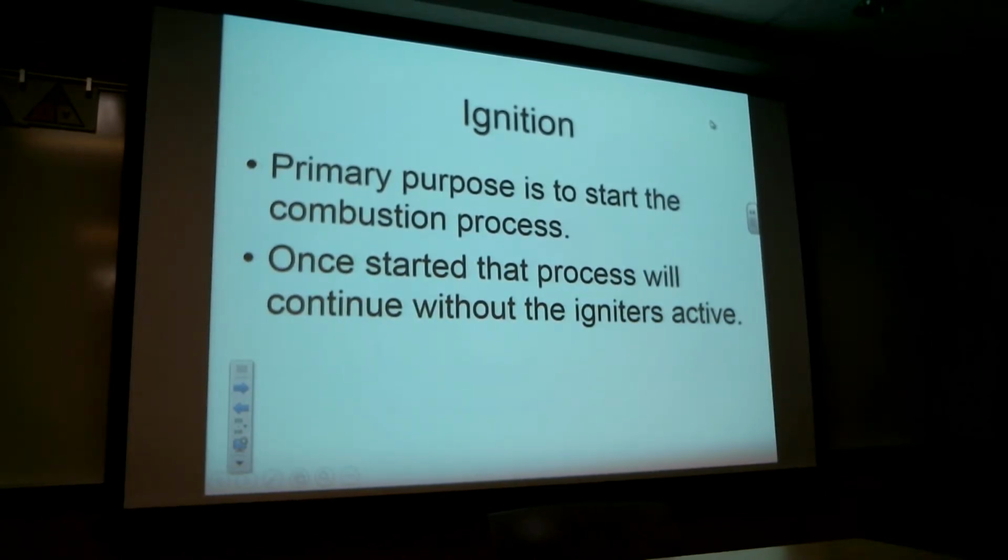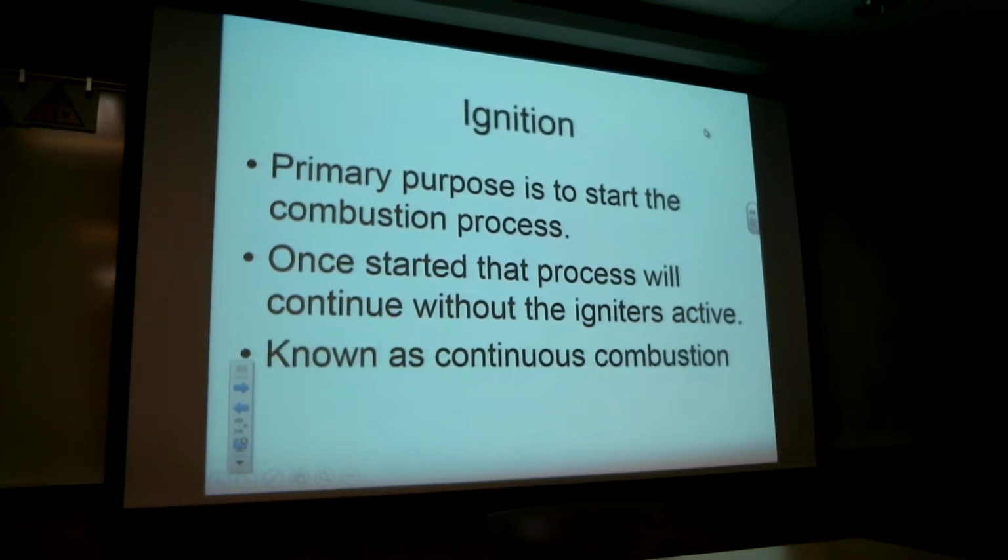Okay, so the only real reason to have this is to start the combustion process. And we're going to use somebody over here that said a starter. Well, we have to have a starter so that we can start moving air through the engine, because it won't move on its own. There's no other way to get it to move except using a starter. The starter doesn't have anything to do with the ignition itself. Again, once the ignition process is started, we can turn the ignition system off.